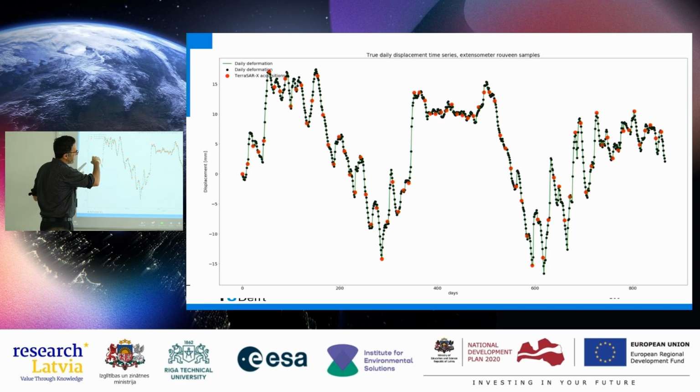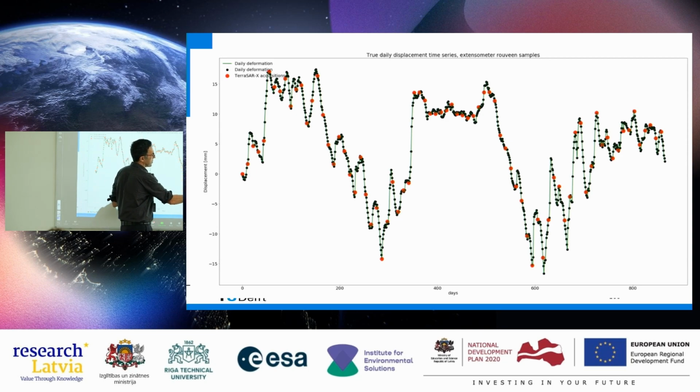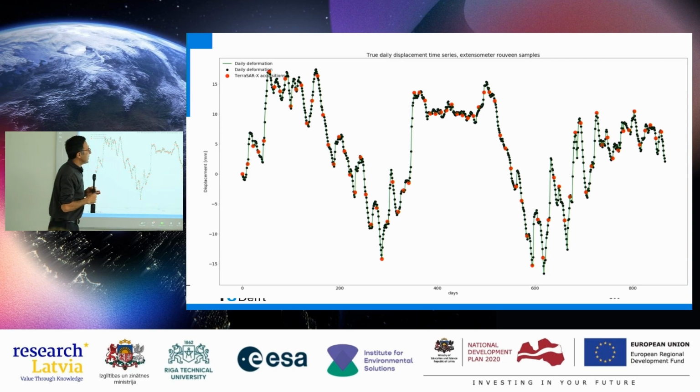So basically the big picture is a pattern which we call hysteresis. Hysteresis is a periodic pattern which is not symmetric, so to say. The drying out of the soil goes very smoothly over here, but then in the fall when it gets wet, it goes up very, very quickly, right? And then it's winter time, and then summer comes again, it dries out, and it goes up relatively quickly. Okay, so the first message is that this is extremely dynamic motion, right? 3 centimeters up every cycle.